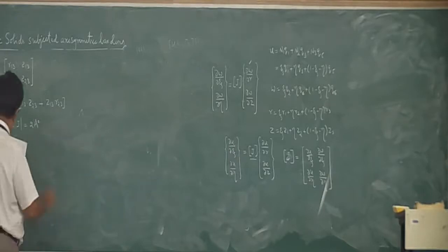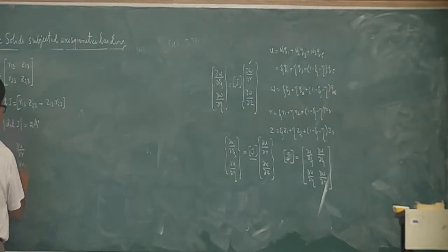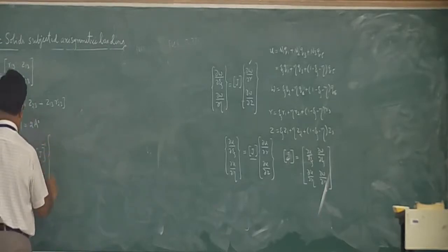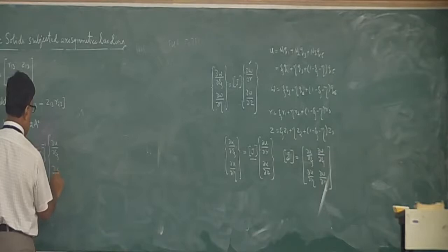We already know this. So this is another important relation which will still be valid in the case of axisymmetric solids also. So now let me find ∂U/∂R and ∂U/∂Z, what we need from that figure. If you take the first one, obviously I have to take the J inverse of ∂U/∂ζ and ∂U/∂η.